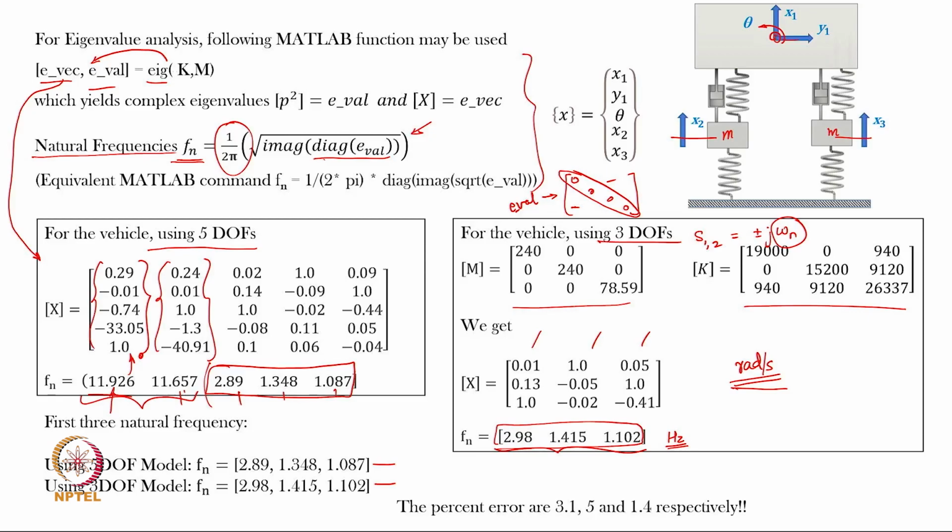Now, we have discussed this in terms of that winch problem, where the higher natural frequency is far apart from the normal lower natural frequency, and so it depends upon what frequencies are excited in this system. If the excitation to this system is lower than, let us say, 3, 4, 5 hertz, then these frequencies may not really influence the total dynamic response.